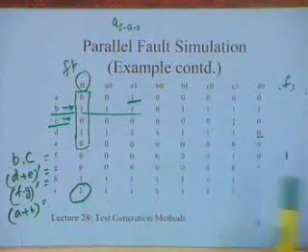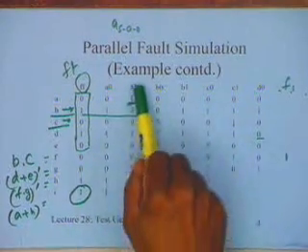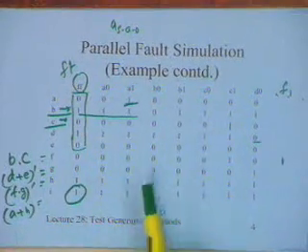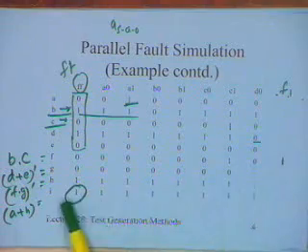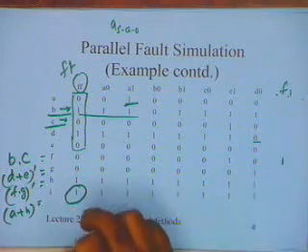So I just perform this evaluation. What I am doing is fairly simple. I am just computing the value of the outputs given the inputs. Under simulating the fault, I am assuming that the circuit has that fault. In this case I am assuming the circuit has fault A stuck at 0, in this case fault A stuck at 1, and so on, and making a comparison between them.